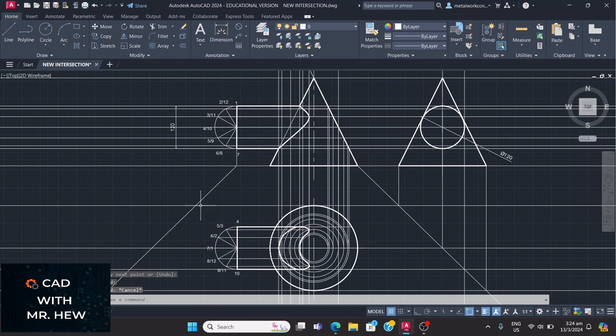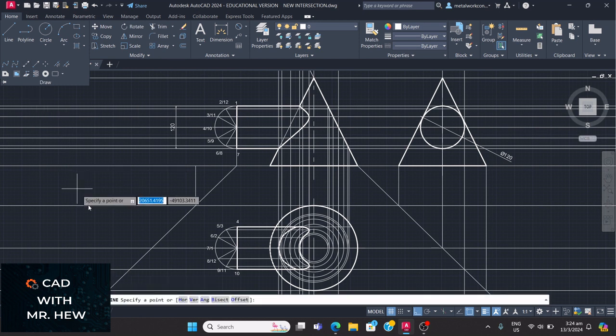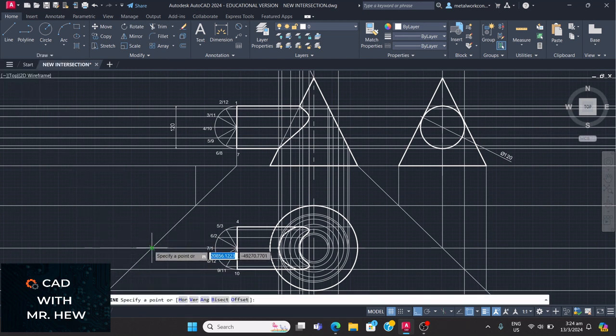So we're going to go line at this intersection. I'm also going to cover the perpendicular. I'm going to turn on ortho, enter. Right, we're going to carry up the center line. The center line we can use the X line because it will be easier for us. Enter. I didn't carry it at the base because I only need the line up to here.